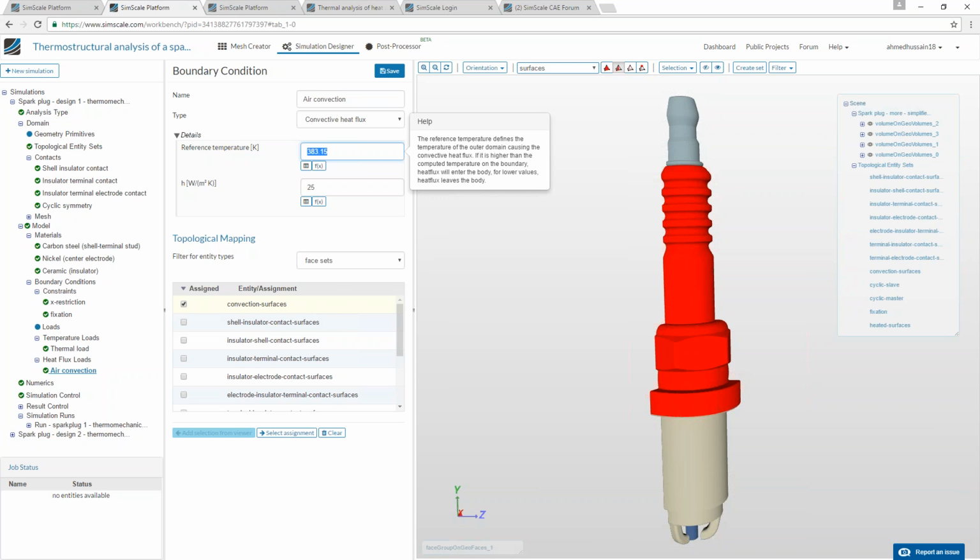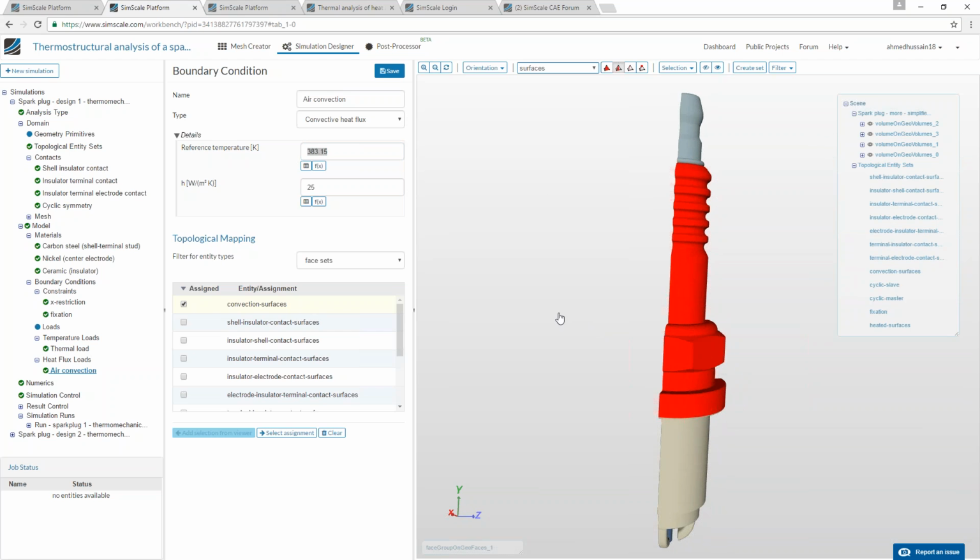But in the case of thermal analysis or thermostructural analysis, it's recommended, since if you don't have a conformal mesh, then the distribution of the stresses and the temperature would be odd, since the solver wouldn't be able to solve it perfectly, as the nodes are not sitting over each other. Then you will see some nodes have less temperature and some nodes have more temperature, and because of that the thermal load would be different, and that's why the stresses would also be different.